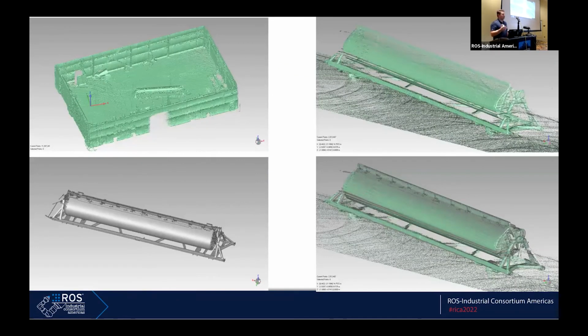Here's a quick breakdown of how we used some of the data that was streaming back from those LiDARs. You can see here in this first image, this is just a giant cluster of data that has a giant radome in the middle of it. We used RViz to kind of develop some different clustering ideas. So we'll take clusters of points, we'll associate them together, we'll compare them to this STL model that we have.